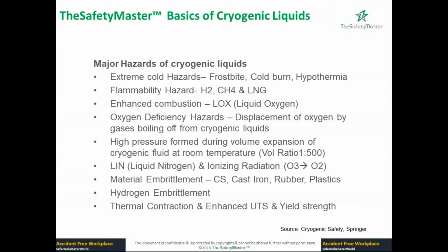Enhanced combustion: the LOX, or liquid oxygen, is associated with enhanced combustion. Oxygen as such doesn't have flammability. It's not a combustible material. The problem is, the moment you pour liquid oxygen onto a material, let's say you pour it on Teflon, the Teflon will catch fire.